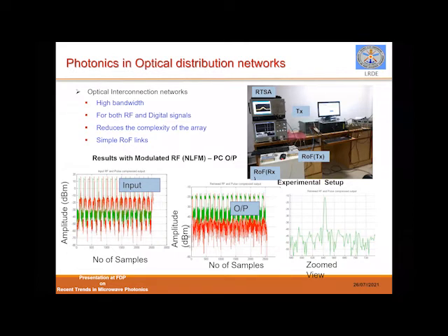So in this case, you need not worry about the outputs, but I will try to explain. You assume that I am sending multiple pulses from this exciter. This green is actually the envelope of the actual signal. You assume that inside this green there is an LFM signal. LFM means linear frequency modulated signal. And when I do the pulse compression of that, at the fag end I will get a peak, because pulse compression is nothing but a matched filtering process. So this is the input and this is the output.